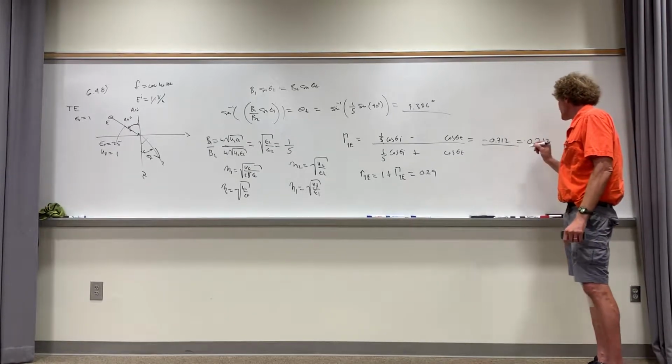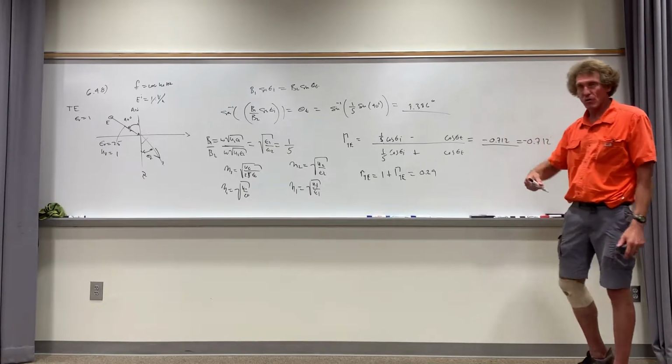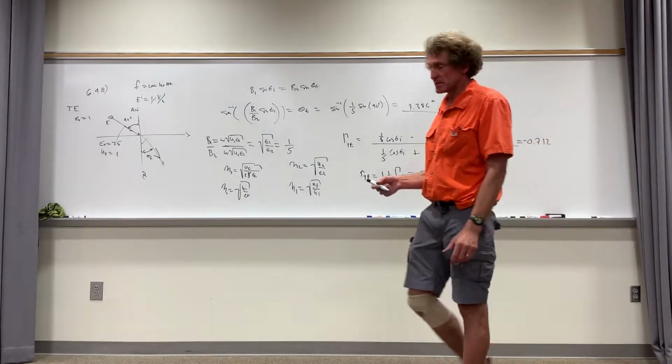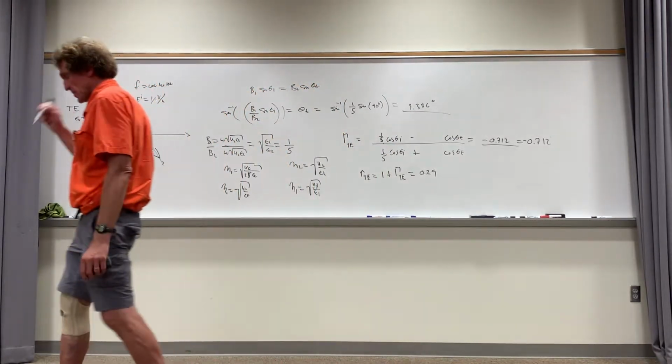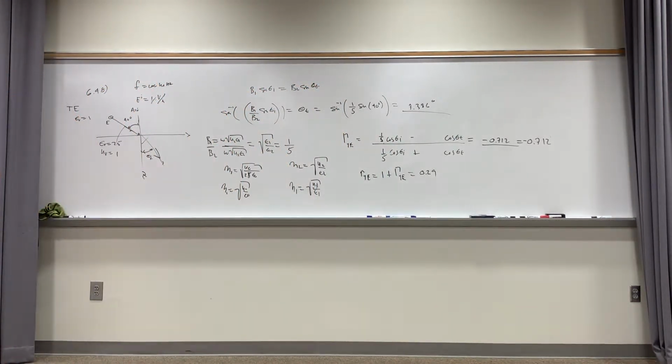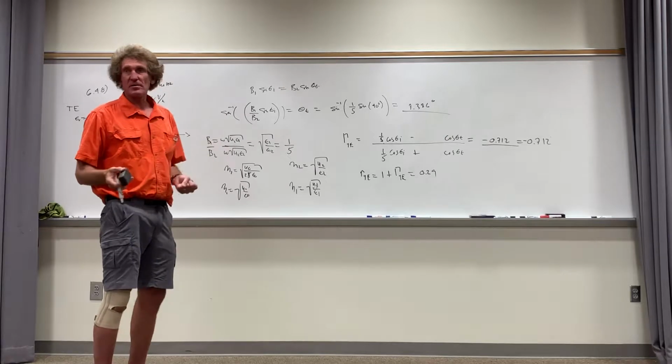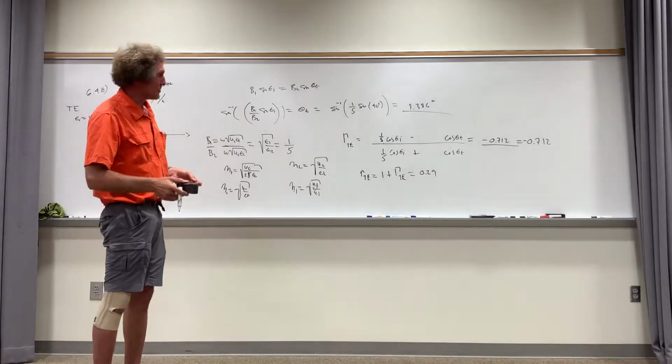Just leave it as -0.72 and put that in as a coefficient where you have E naught transmitted. You know the equations, but I don't expect you to give me the equation with all that, where it'll be e to the minus j beta times x sine theta transmitted plus z cosine theta transmitted. Do you follow me on this, class? I'll just ask for the magnitudes. And the reflection, I'll ask for the reflection, transmission coefficient, transmitted angle. One other thing I want to make sure we're clear on.